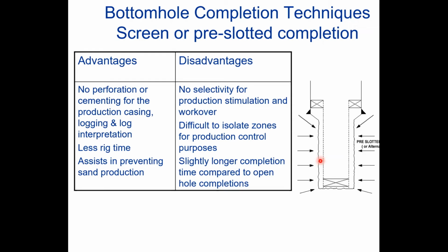That is called gravel pack. The problem with gravel pack is that it creates extra resistance. The other option is to move the screen to touch the formation.